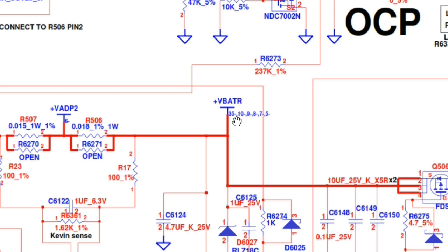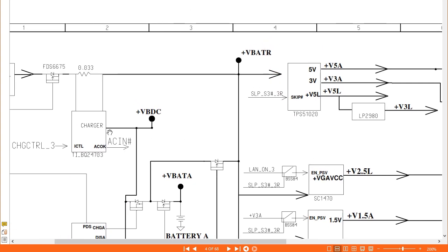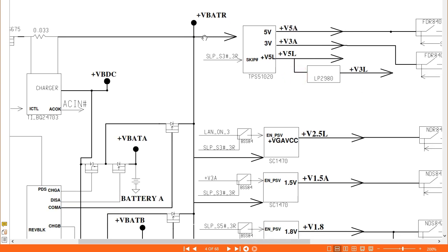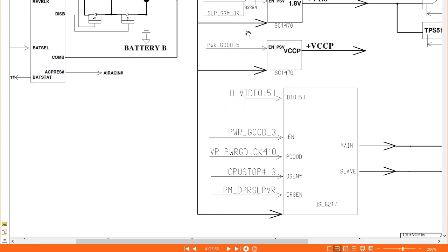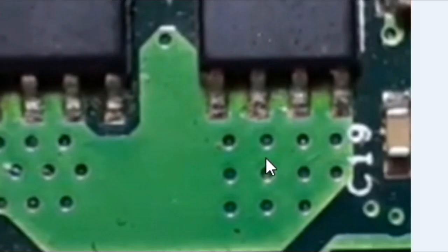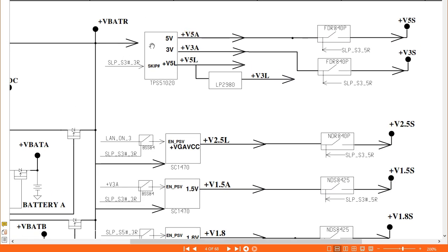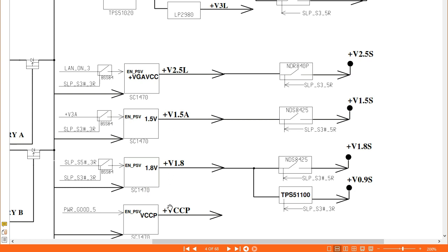In these pages, you're going to find these ICs. Okay, these ICs. After receiving the 19 volt here, it will be distributed to all ICs in the motherboard. These arrows basically mean this point here, and mean also these pages here. Okay, so after this IC receives this voltage, it will generate these voltages. This one also will generate these voltages and so on.